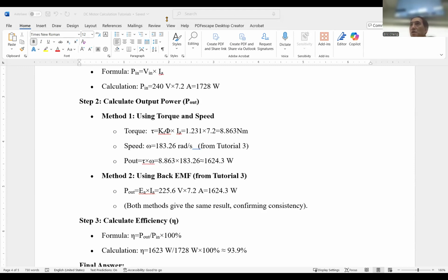So this tutorial is not very complicated, a very simple tutorial, much similar to what we have been doing in the lecture. Over here, you can see that we need to use a chopper to reduce the voltage. So the motor armature will see less voltage using the duty ratio. And then the inductive current for the motor, because there is a big inductor there, we cannot assume the inductor equals 0. We still have some energy holding there.